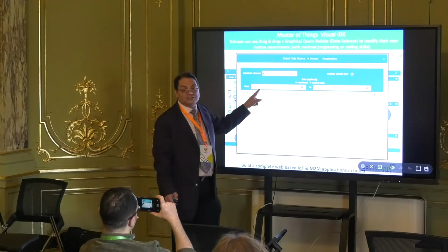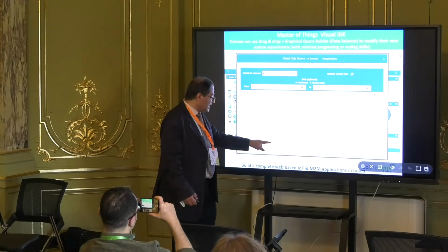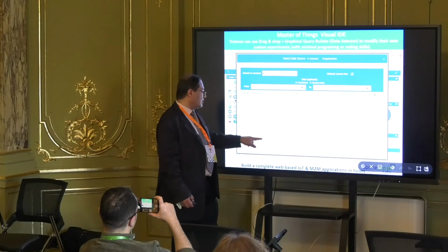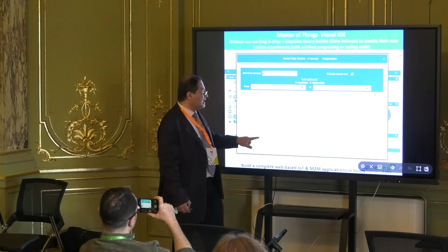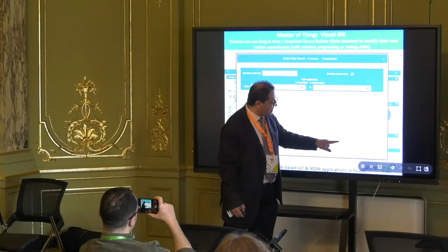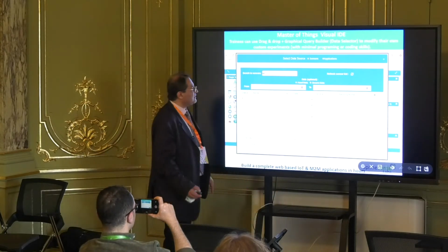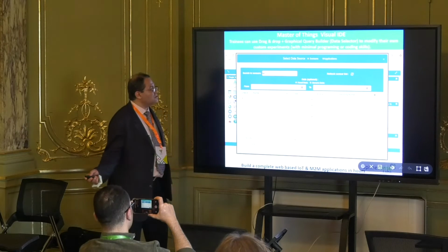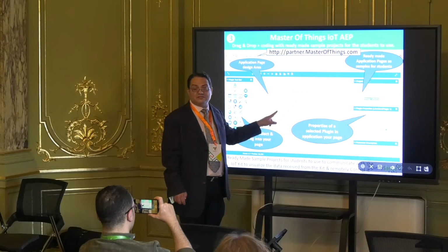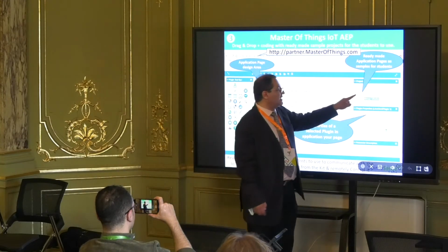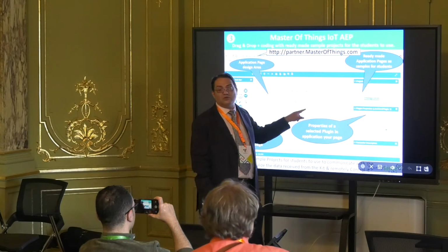And then how many readings you would like to display out of this sensor over the time. So the guy who has been doing this example wanted to show the last 100 readings of the temperature, and he wanted to show it versus the time, and you can also select different time formats. Now, if you've done so, this chart will display the temperature over the time. So you can also give it a name, and you build your web page that will display this temperature.